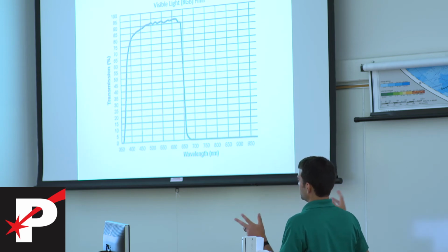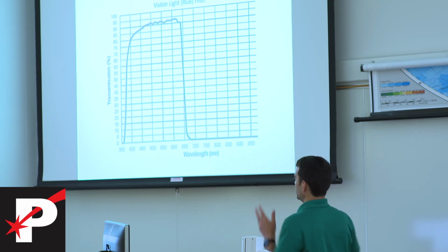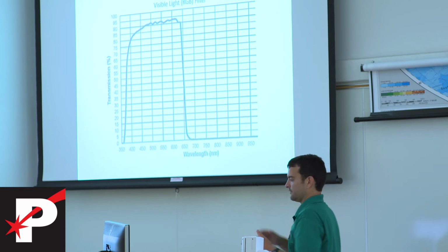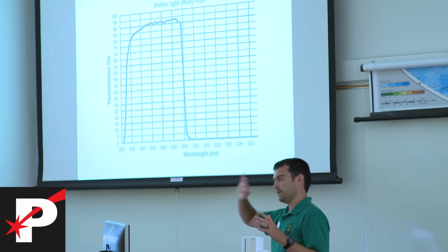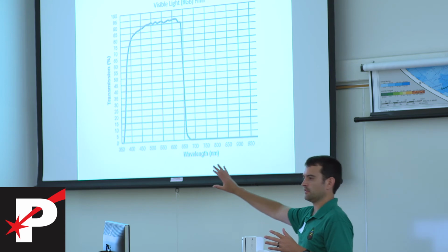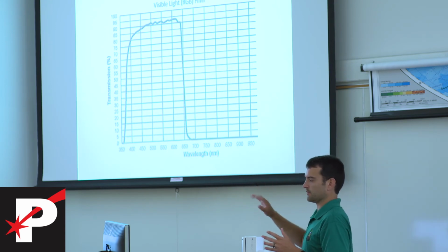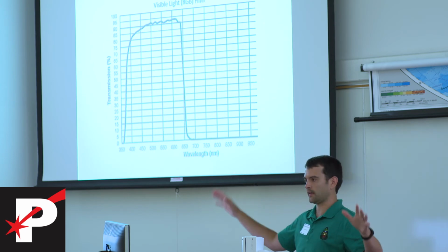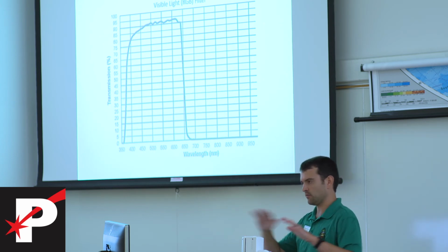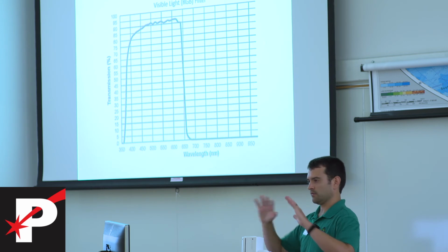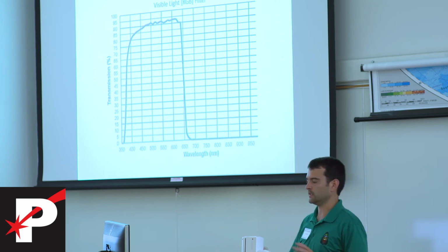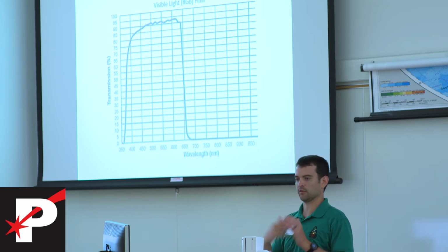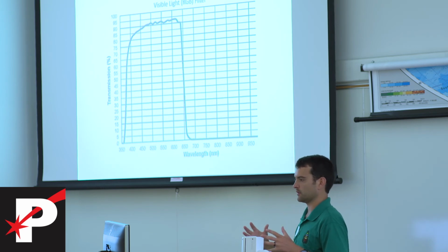So if you remember, the sensitivity of a typical RGB mono sensor is 400 to 1100. If you remember, the RGB curve went out past 700. Well, we don't want that information. Infrared light is really bad. If you were to take your phone and try to capture a picture outside with all the IR light from the sun, it would be the most muddled, very dull-looking picture, with muted colors. All that infrared light would overload the sensor. You wouldn't be able to capture the vibrant color that you would otherwise.